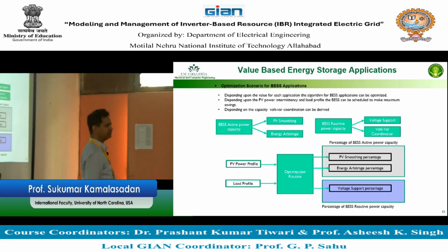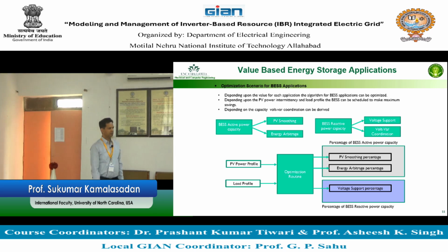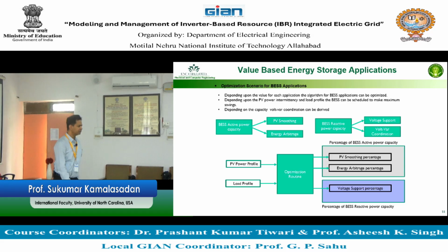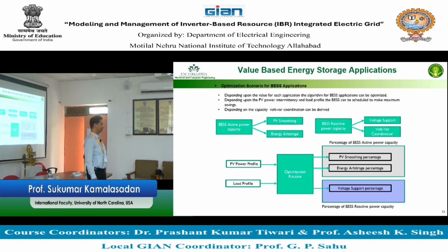Now let me ask you, what is a volt-var control? You are controlling the voltage profile based on a curve for the reactive power, for the voltage, to maintain the voltage with respect to time. So you don't have a constant voltage, you have a changing voltage, say 0.95, and you push reactive power for that specific voltage and change that. That's called volt-var control. There is also something called volt-var watt control. Volt-var watt control is where you are doing volt-var and you are also doing watt. Watt means the active power coming from the inverter.